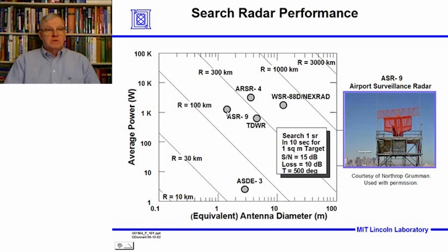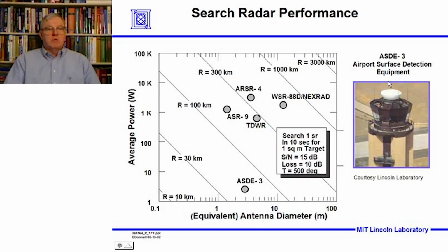Okay, now let's move on to another radar. This is one that's located at most major airports, and most of the time it's located on top of the air traffic control tower, where air traffic controllers visually look at what's going on at the terminal. So it's several hundred feet tall. It operates in the so-called Ku band. It's the lower portion of the microwave band, a wavelength a little under approximately 2 centimeters, a centimeter and a half. It's 16.5 gigahertz approximately.